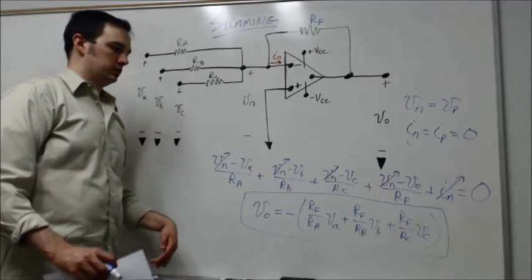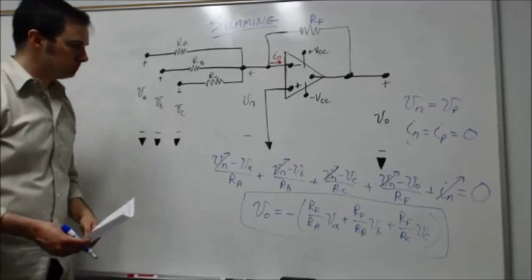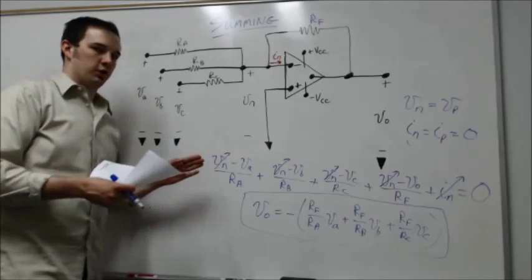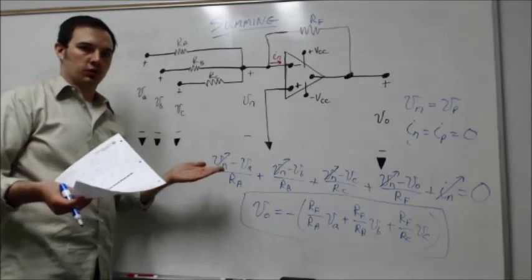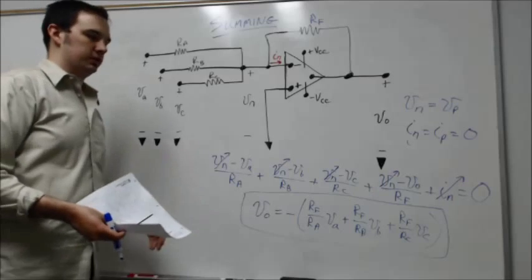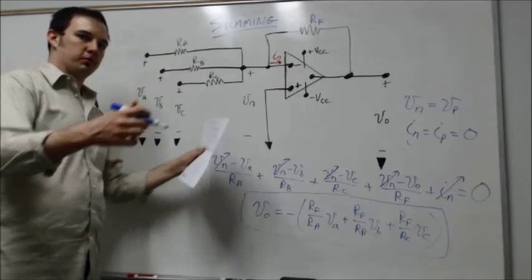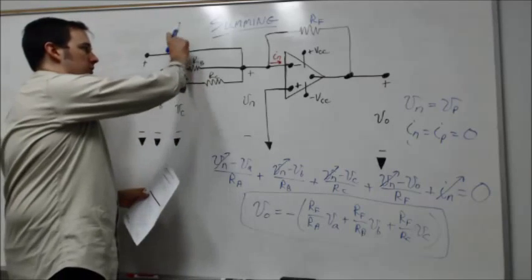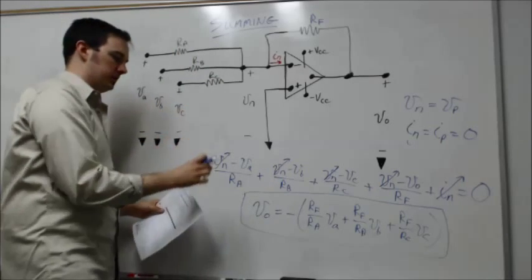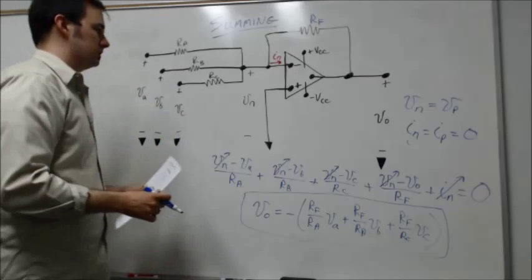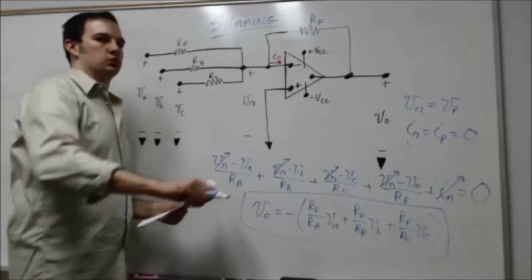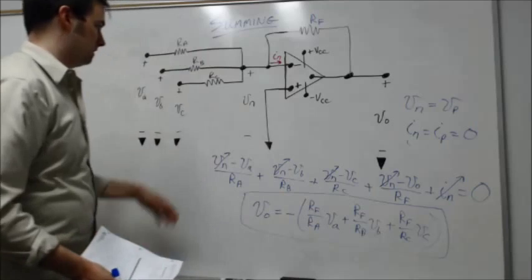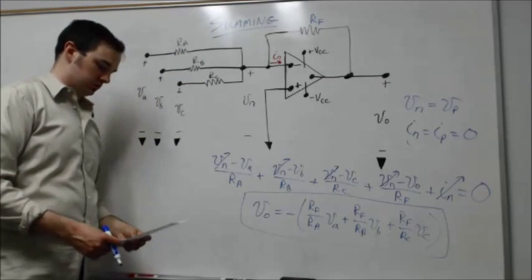A specific application of this type of circuit could be audio mixing equipment, right? Where I might have a guitar, a microphone, bass guitar, keyboard, or whatever. Each of those inputs is essentially acting as a source, a potential, because the signals are being converted into voltage signals. Typically on a mixer board, if I'm plugging all those signals in, each channel would have a specific gain, which is basically just a variable resistor sitting in there. So I can tune each given input to raise or lower the volume, giving each one a specific amount of boost. And then on my output, where I might be connecting my speakers or my recording module, I'm simply adding all those input signals together, relative to their given gains, based on however I'm tuning that in my fancy mixer board, okay?